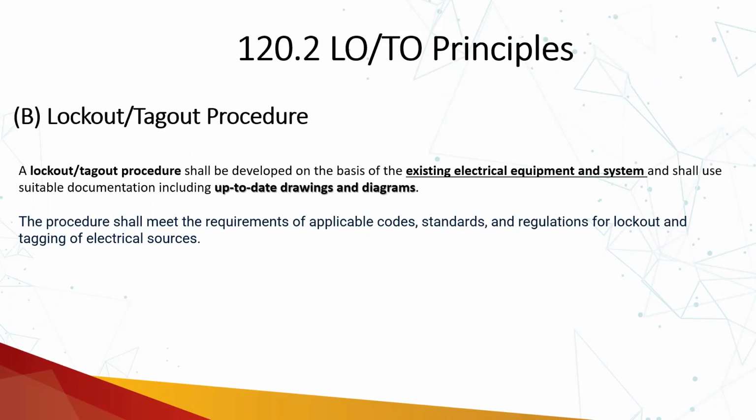So next time if you want to create some shutdown, you simply put off the breaker and then you think that the outgoing is closed and you can go in and perform the work, but actually that supply was direct. It was not through the breaker. So those things need to be updated in the single line diagram, the correct status of the network.